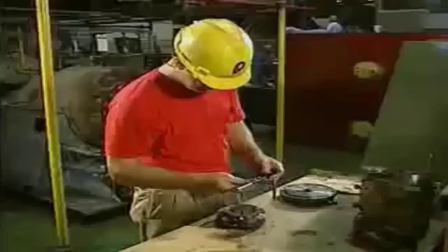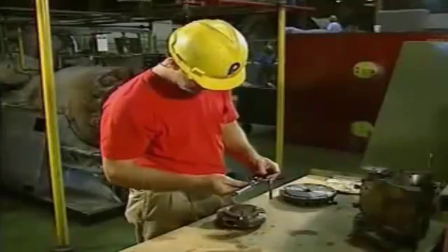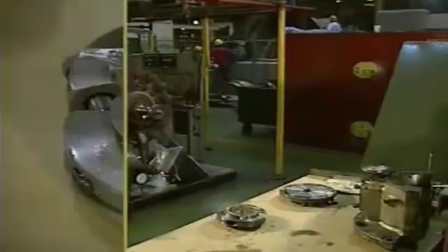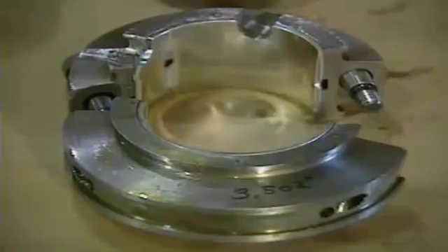To obtain the total clearance, the mechanic subtracts the diameter of the shaft from the inside diameter of the bearing. If the total clearance is too great, the bearing inserts are replaced and the test is repeated. If there is too little clearance, the bearing is either replaced with a bearing of the correct size or else it is scraped down.